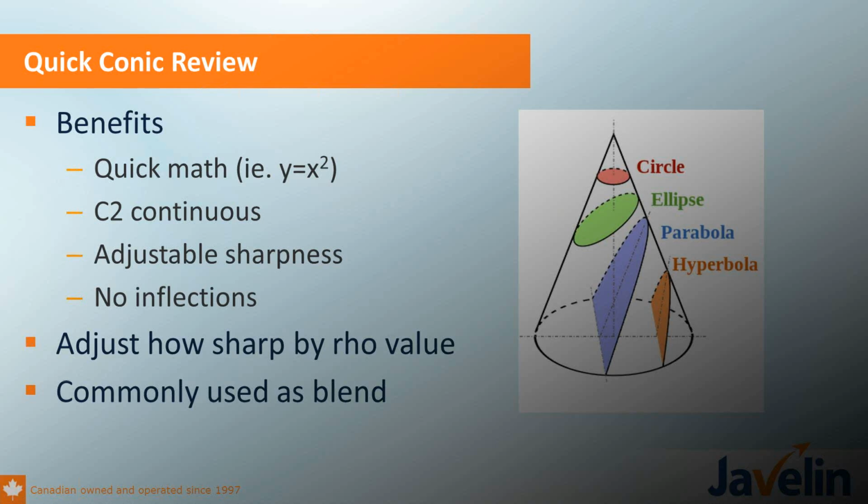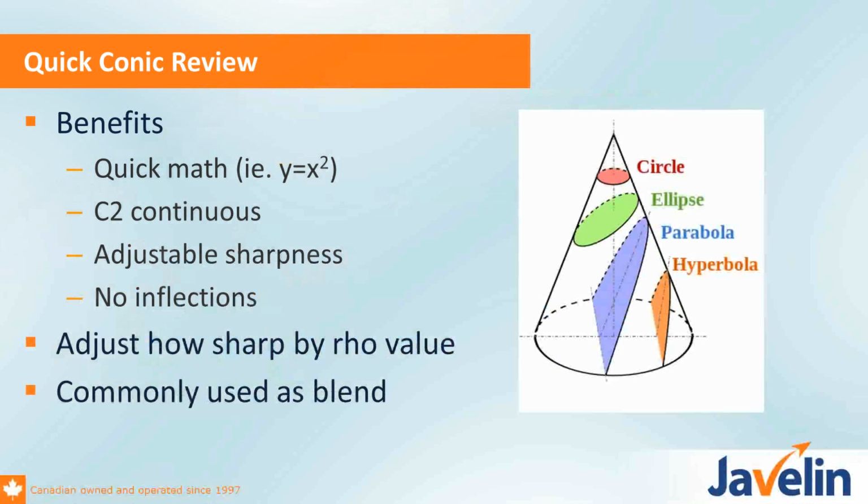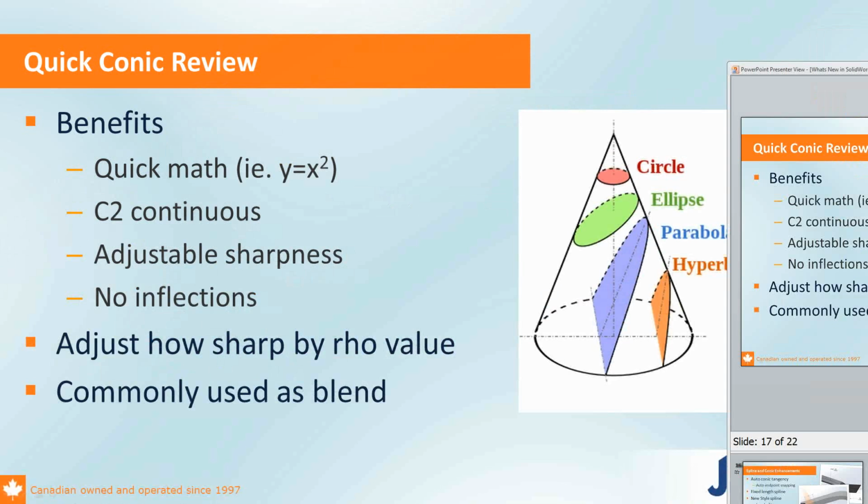So overall, the style spline is just a little nicer way, and again, you can use the replace sketch entity to go and actually replace one sketch with another, and it will reestablish all of the links, and everything will be fine. So definitely look for those in your sketching in 2014. All right.